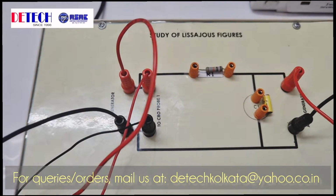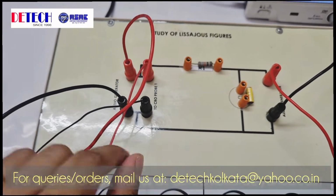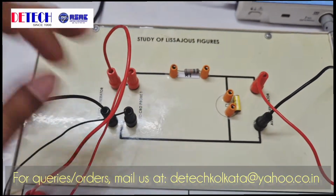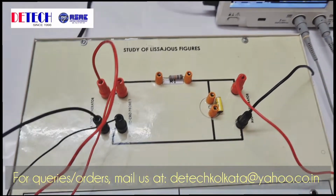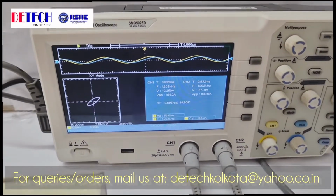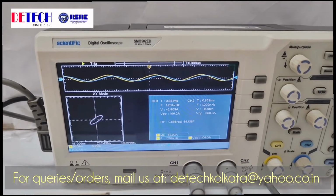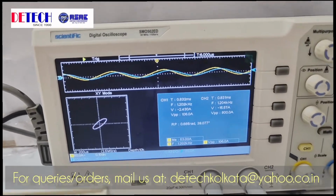So now I've connected the circuit in order to study the phase and the magnitude relationship. What I've done is I've connected the audio output over here, and I've connected the channel 1 of the CRO over here, and the channel 2 of the CRO goes over here. And I've adjusted the frequency so that we have got a frequency of 1.2 kilohertz, and the phase difference between the two signals is almost 45 degree, and that is why we obtain a figure like the one shown.